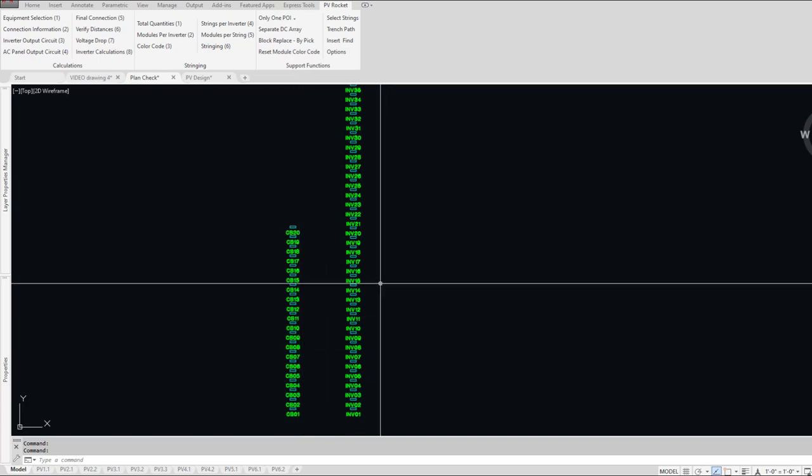So I describe the other people's project to PV Rocket. I get to the voltage drop box, and if they upsized things, I'll go up on that and get it to the right place and hit save, and then I get to the print, and I'm very focused on the feeder schedule and the calcs. And what I find a lot is violations of Article 250.122(B).